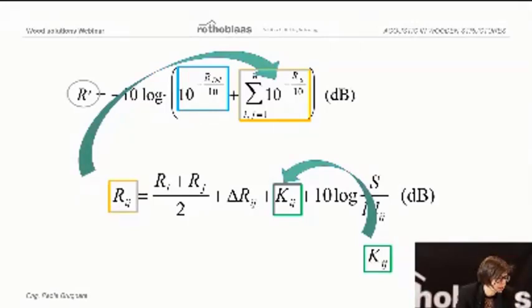And then there is this Kij, which is, as I said, the vibration reduction index, and it defines the influence of the connection on the propagation of vibration. So it is very different if we have walls and slab connected with many fastening systems, if we have or not a resilient profile, and so on.